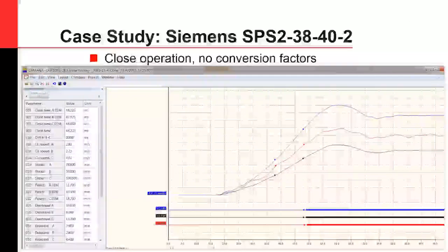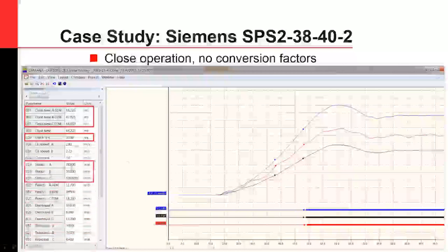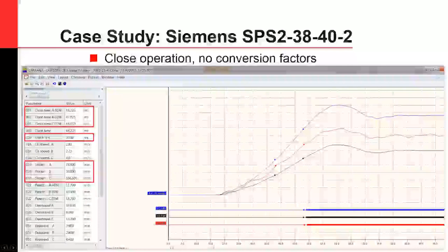So we went through and made a measurement with this, and you'll see three completely different motion measurements, although all three of our times are fairly close. You have 48.2, 47.9, 48.0. So really the difference between phases is only a third of a millisecond. But looking at motion, those are all quite different. We'll see 78.9 for linear A, 59, and it says millimeters, but what I did is I decided that 1 degree was equal to 1 millimeter just to make it a little bit easier.